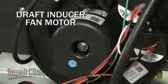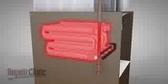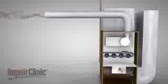The first system uses a draft inducer fan motor to draw air into the burner assembly. The air allows the burners to warm the heat exchanger. The air within the burner assembly is then exhausted to the outside of the home, which is necessary since this air contains toxic fumes such as carbon monoxide.